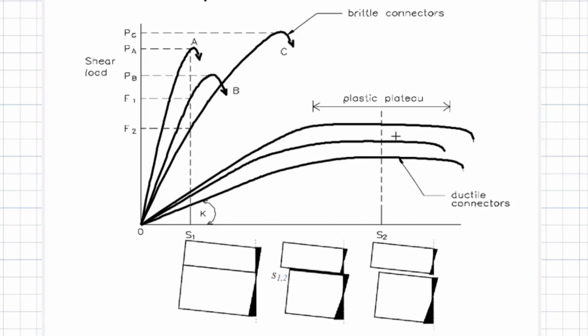Ductile, the one which I showed you, the channel standing straight, and the stud shear connectors. The other one is the block shear connectors. We say a T and a channel put in the horizontal direction. Now, this is the behavior. You can see here, the rigid shear connectors give you a very high strength, but their failure is explosive.